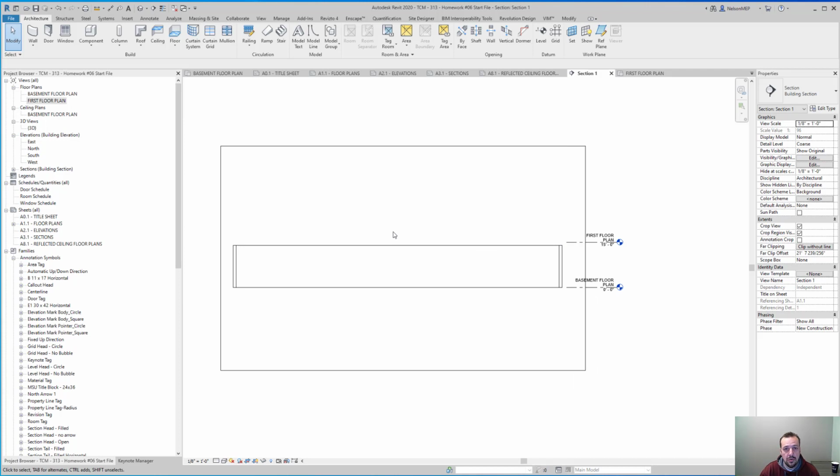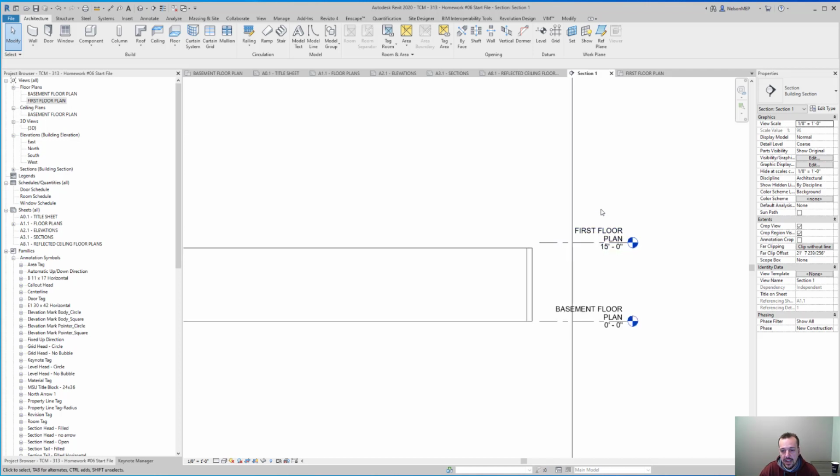All right, so next I'm going to create another level. I will call it the parapet height. Or not the parapet, I'm going to call it the eave height. If you think about a house, or the structure we're looking at, since we're doing a pitched roof, we want to set an eave height, which is where our roof comes down and lands. So I'm going to set that eave height, and that's going to be our next one. I'm going to set that at 15.